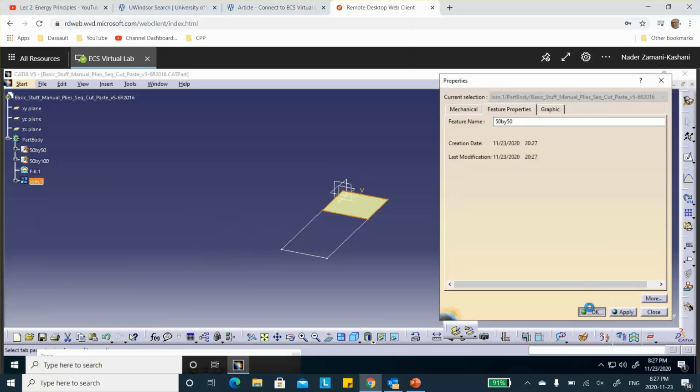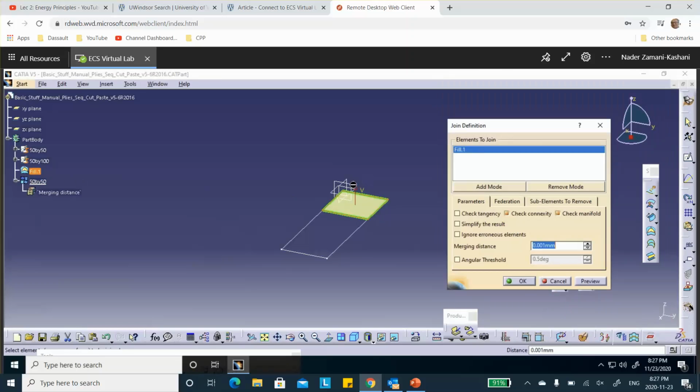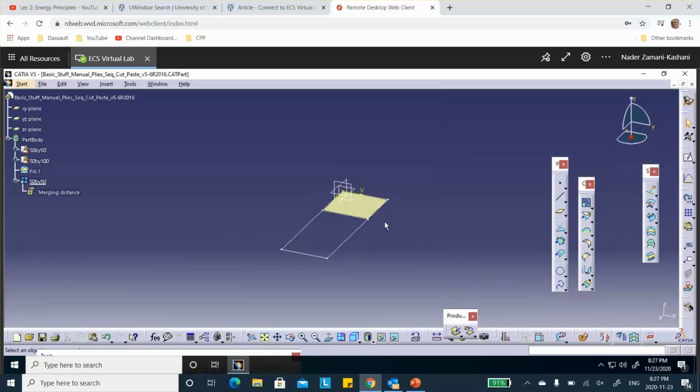Okay. And based on the stuff that we have done before, when you join, you get an orientation. I'm going to flip the orientation so that the orientation of join is down. And because of that, every time I create a shell mesh up here, its normal direction, the third direction to the shell, is going to be up, opposite the join.